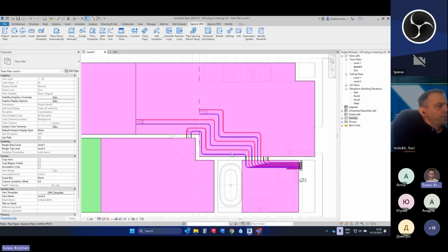That's how we can move these feed pipes. Okay, before I connect this bathroom and before I generate the loop, I need to do one more thing. I need to cut out the areas that are covered by the feed pipes. So if I generate the loop in this area, the loop will not be over the feed pipes, right? In a second, I will also show that, because I remember you told me that in Ukraine sometimes the feed pipes go inside of the installation, right?